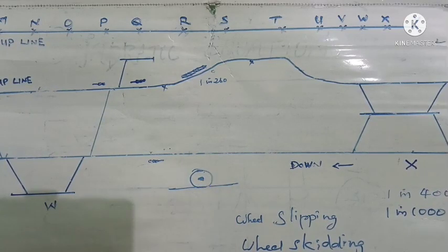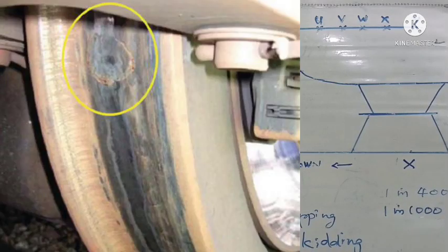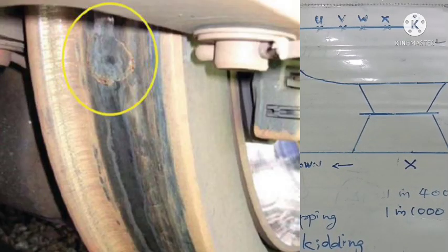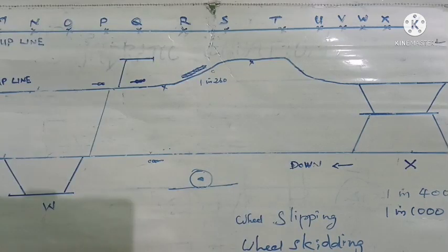In such cases, we call it a flat tire. The wheel is having a flat tire. Instead of having a perfect round, this portion will be flattened. When we see a train having this thud sound, we can understand that the wheel is having a flat tire. The jamming of the wheel can be due to brake binding also.